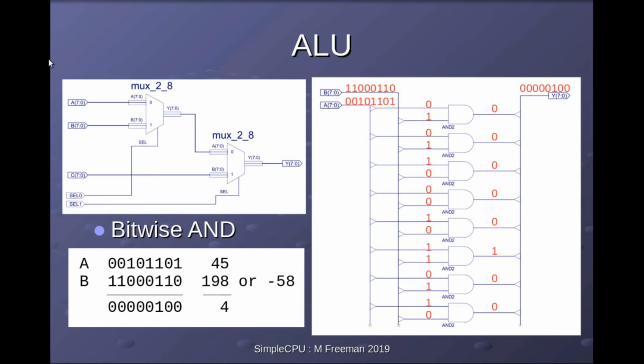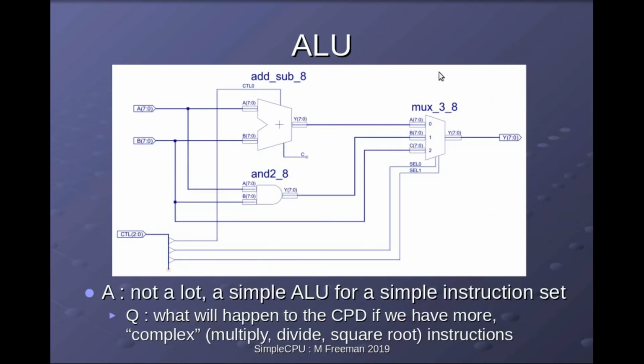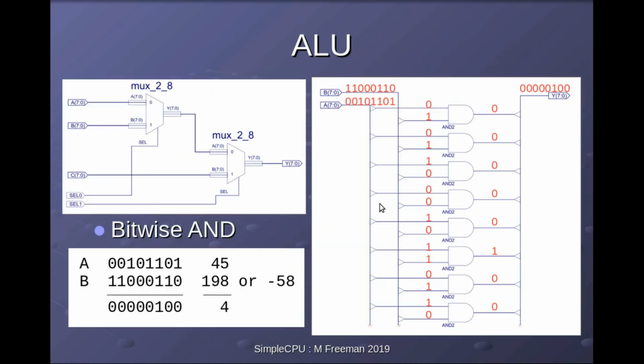And finally, we have the 3-input multiplexer that generates the output of the ALU. So if we go back and look at the ALU schematic, that's the symbol for the 3-input multiplexer. Each of its inputs is an 8-bit bus. So to implement that, we take our standard 2-input multiplexer. In this component here, we have 8-bit multiplexers, multiplexing each bit of the 8-bit bus. And combining these together, we can make a 3-input 8-bit multiplexer.